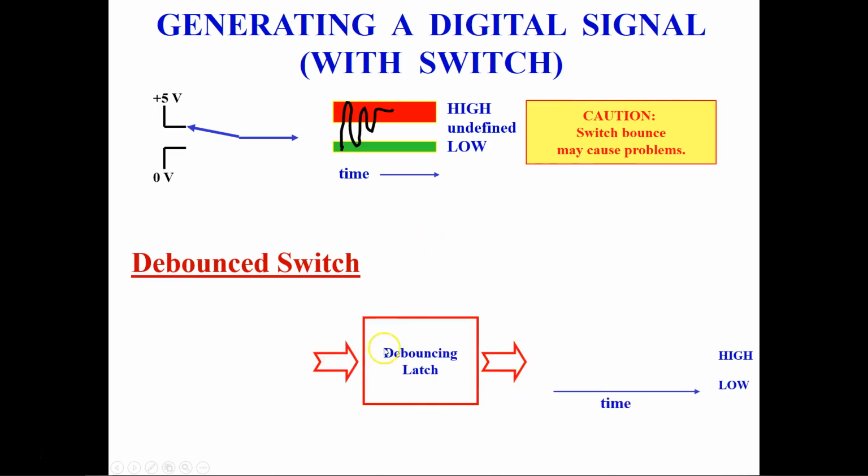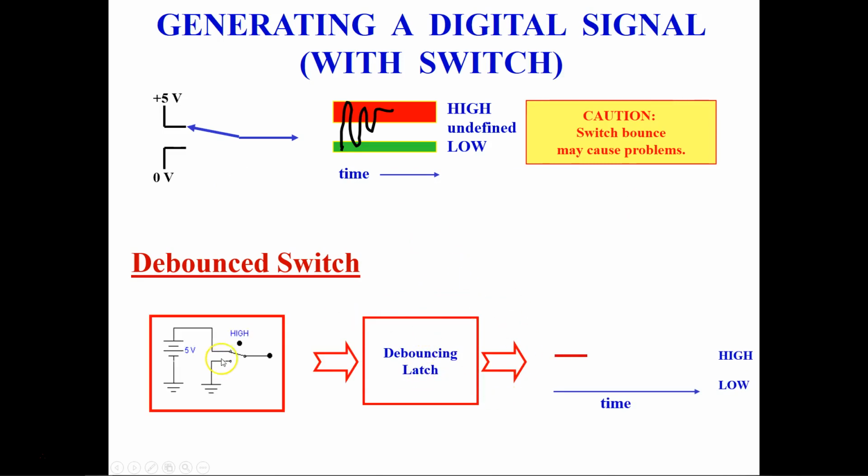This is the block diagram of the debounce logic switch, and as you can see here, this is the mechanical switch toggling between low and high. You can see now it is low, so it is the low range, so it is latching the output which is coming here, and then when it is again high, then latching it at a higher voltage, and then again low, and so on. So here the use of a debouncing circuit or latch is very beneficial.